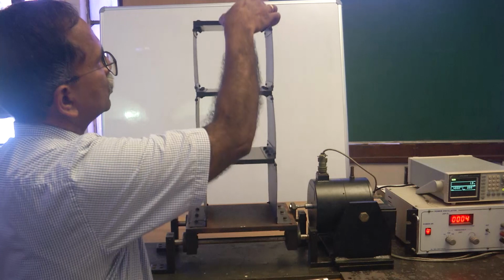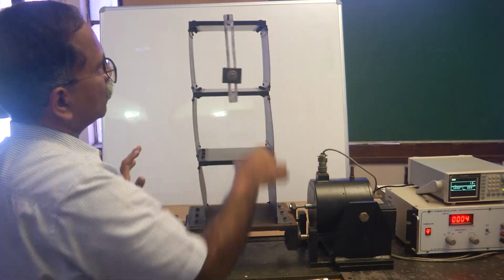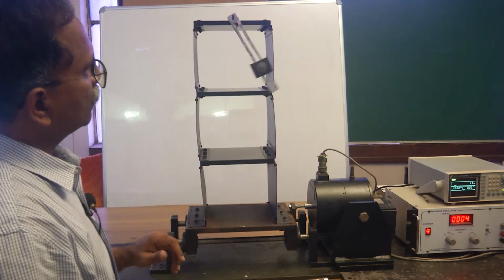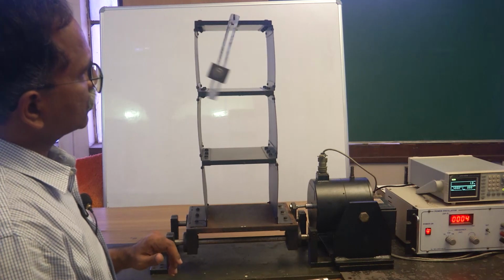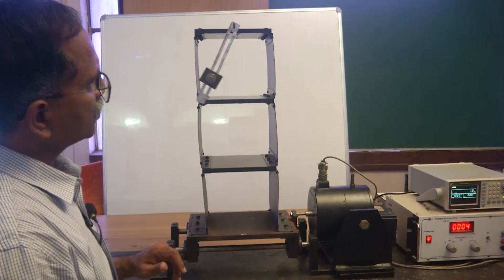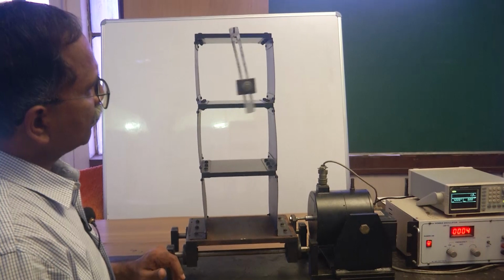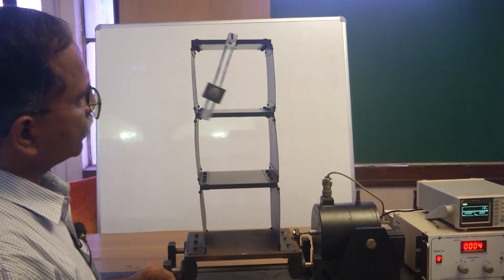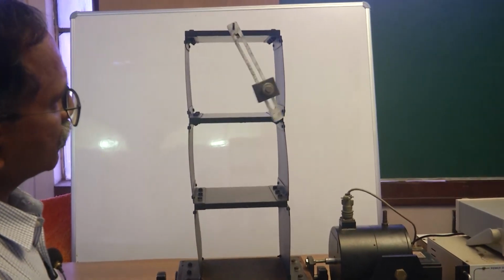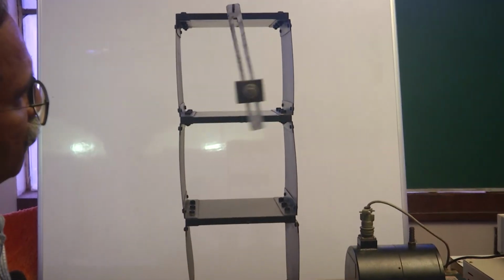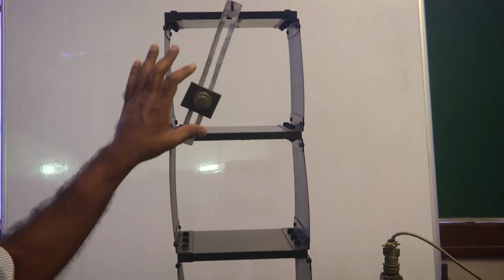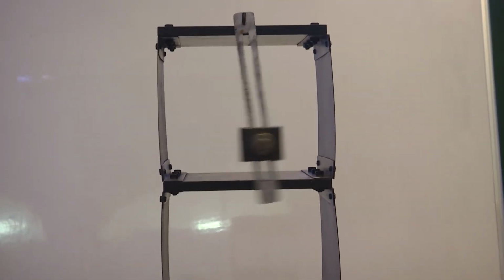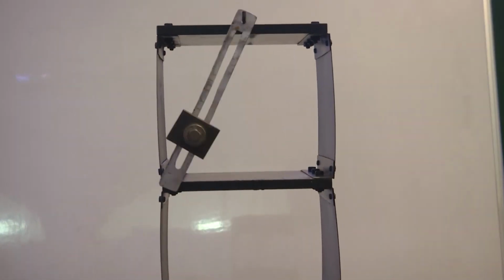So I am going to attach this pendulum and see if the parent system vibrations are brought to 0. Compared to when the pendulum was not there and the system was vibrating at its first natural mode, the amplitudes were very large. By attaching this absorber, you can see that the vibrations are not exactly 0, but they are much smaller.